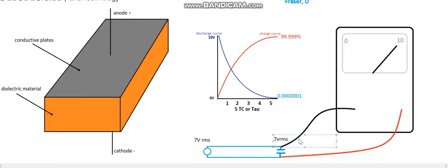But what is 7 volts RMS to a capacitor? It's really 10 volts peak, isn't it? To a capacitor, because that's what it's seeing. It's seeing the total value of charge. Now, an RMS value is just a root mean square plotted across that sine wave. But a voltage peak, hey, that's a lot more. That's 10 volts. So that's why, as you add more capacitance, the value of output voltage in these circuits that we're going to be doing starts to increase. Okay, which is kind of cool.